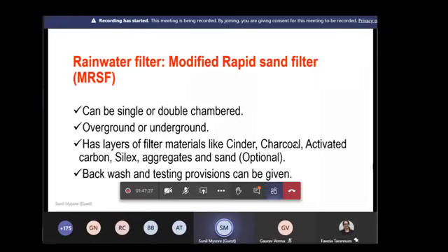So the best way to filter this is a carbon filter. There is definitely going to be some amount of dust and some amount of gases which you need to take care of, particularly in areas like Delhi and northern Karnataka, where you've got power plants. Essentially, we pass it through a large bed of activated carbon. It's the same thing you might be using in your normal filters, commercially available ones, which have a cartridge made of activated carbon.